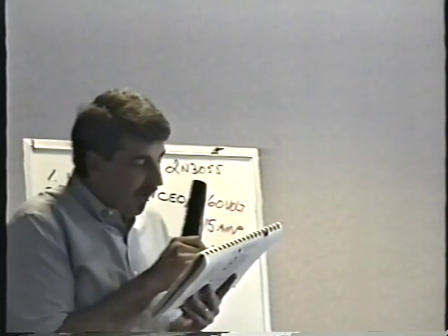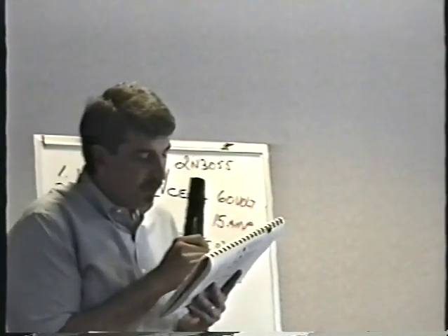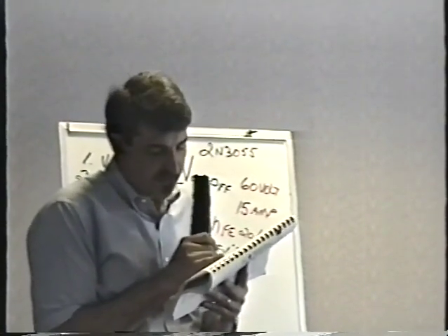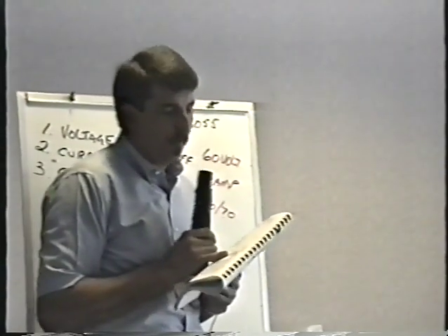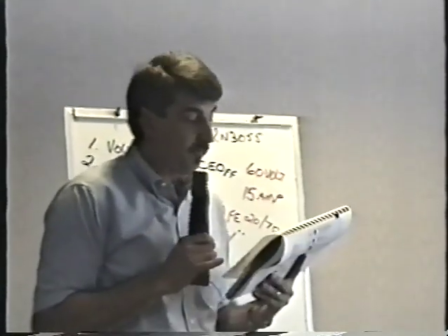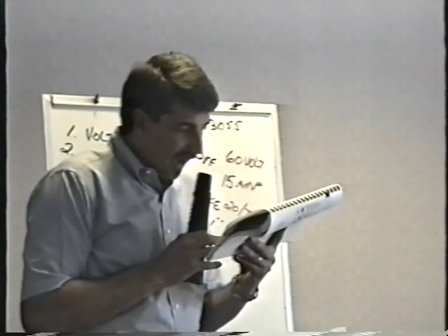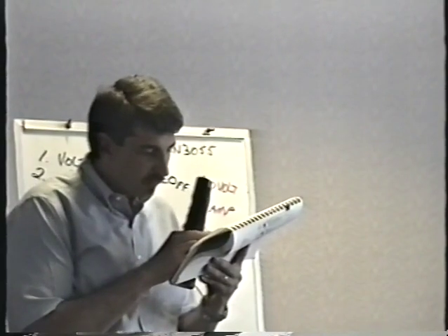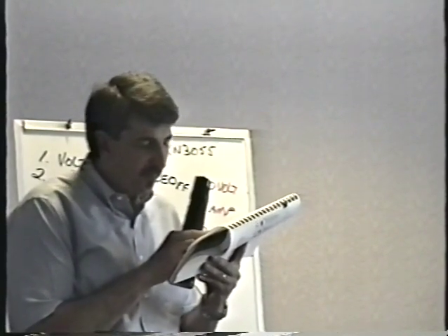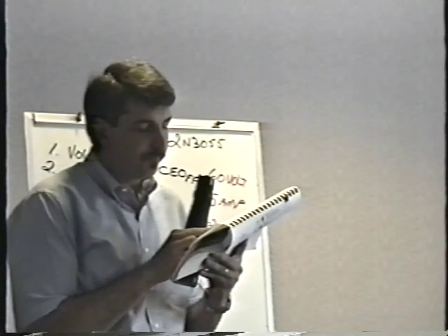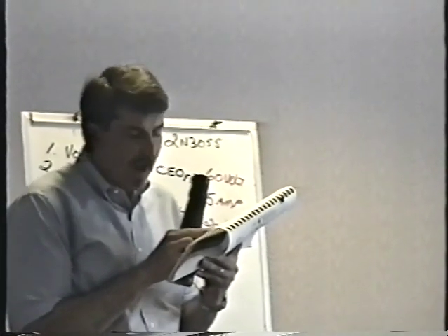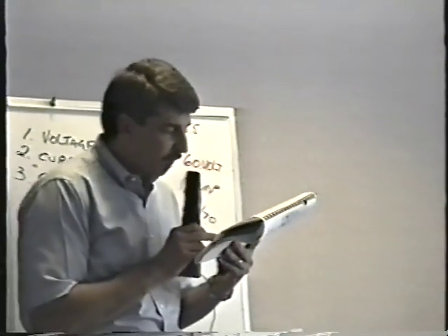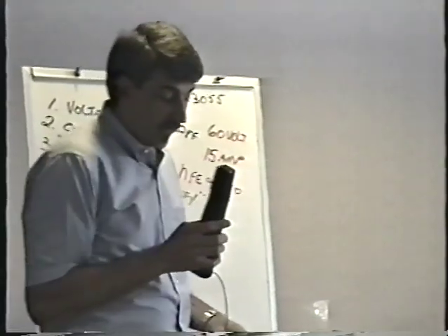Let's go down 15 amps, 350 volts. 2N6251, no problem. It's a low gain transistor, and it says 6 to 50, but that's still in the ballpark. That would work. It would be very expensive, but it would work. Let's go really nuts. 20 amps, 450 volts. MJ13334, no problem. See, it's higher current, way higher voltage. The gain is 10 to 60. Okay? So that will work too. And so that's really all you have to look at.